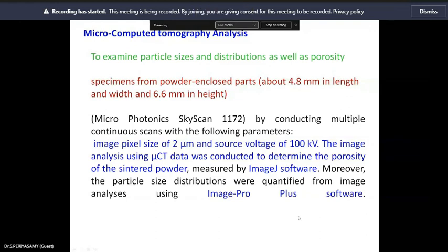Given the commonly unfavorable effects of the residual stress, a subdivision of the scanned area or smaller scanning sections, then heating of the substrate, and then post processing can be employed to mitigate the residual stress. Heating the substrate is either uniform or not, then you have a forced process to relieve it.